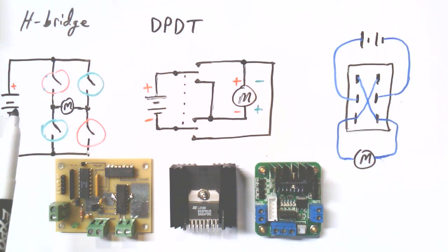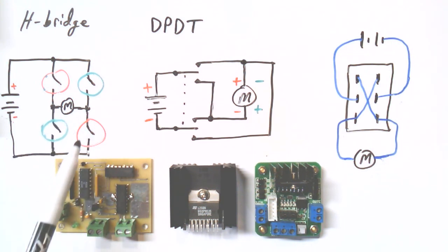I mean, if you have four poles in a motor and you're trying to switch a sequence, or in some stepper motors there's just two coils, but the sequencing is one coil and then reverse polarity on that coil, then the next coil, then reverse polarity on that coil.